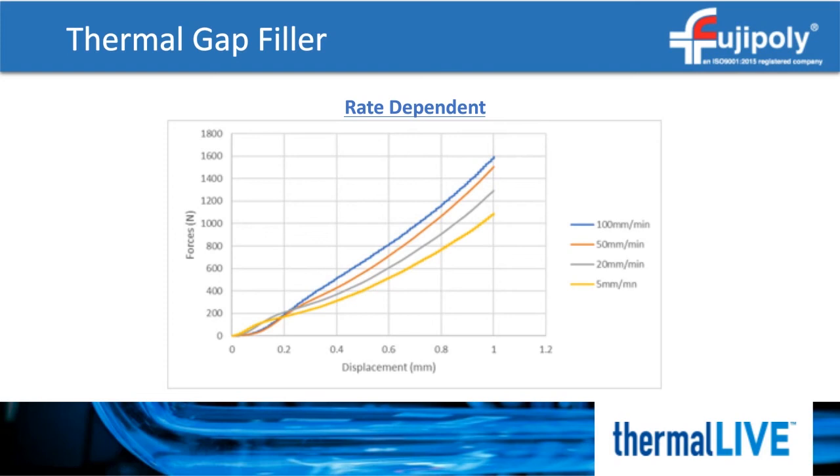Putty pads are not reworkable. Once they are compressed, they should not be reused if there is some rework. Even viscoelastic pads should be replaced if there is service required. Because compression is so critical in a gap filler application, reusing even a viscoelastic pad can mean under compression, since the compression set becomes worse over time and temperature.